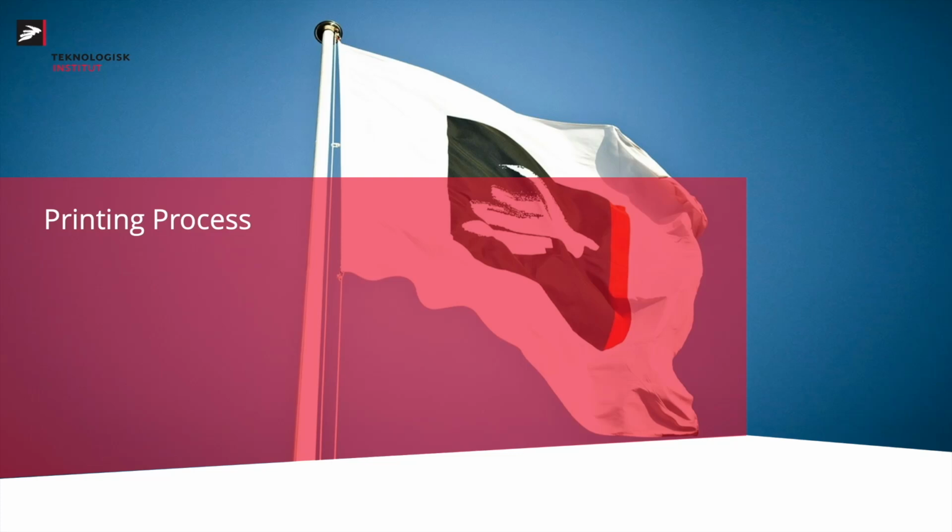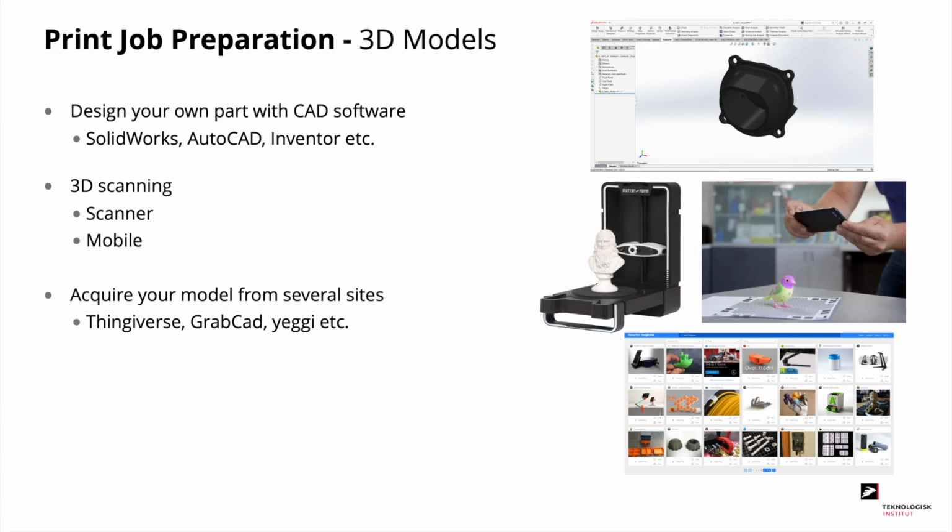We looked at 3D printing itself in a previous chapter, so now we will have a look at the 3D printing preparation process. So the first thing you have to do is to get the 3D model that you want to print. You can go ahead and design it yourself in some kind of CAD software. You can also take an existing part and scan it, either with a scanner or your mobile phone. And finally, you can acquire a model on one of the many online services out there.